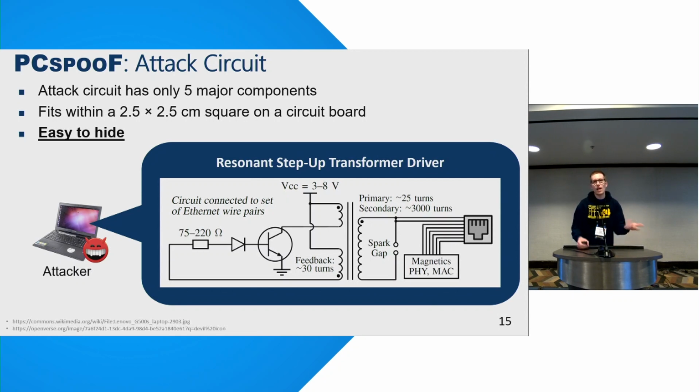And because of that small size, it means that it's within the realm of possibility to hide this sort of malicious circuitry in something like a commercial off-the-shelf device, especially if you consider that because of TTE's isolation guarantees, that means very commonly, even in critical applications, no one is looking for this sort of malicious circuitry. The assumption is, I have the isolation guarantees, I'm safe. People will do things like swab for explosive residue, they'll do burn tests to see if something represents a fire risk, but getting to the level of doing individual checkout of components on a PCB is not very often done.